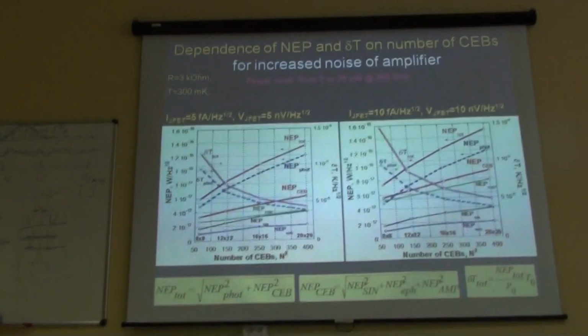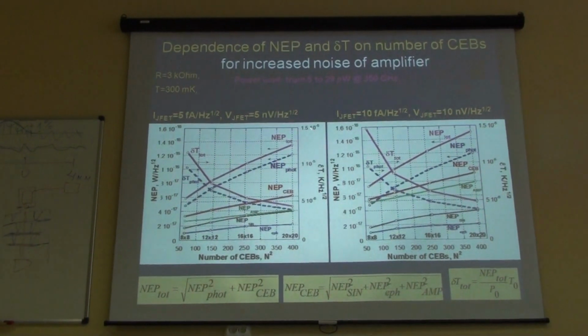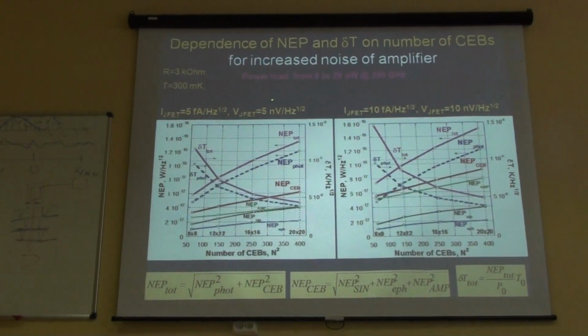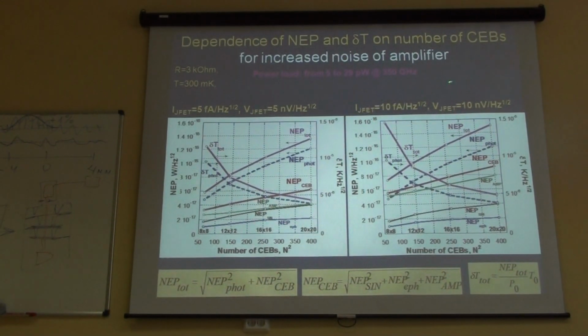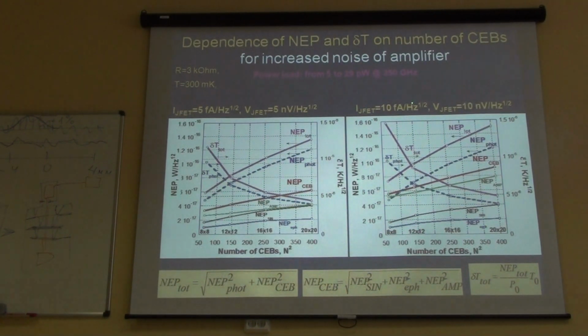You see, it's two types of amplifier noise. This is ideal for AD743 when we use two amplifiers. And let's say that both components are increased 2 times. Before we had this photon noise and this amplifier noise. In that case, amplifier noise starts to be larger than photon noise, and total CMB noise larger than photon noise. It's not so good. But when we move to a larger number of bolometers, we compensate this, and you see photon noise is increased, amplifier noise is quite low, and even if we have additional microphonics noise or something, maybe we can realize still a good system.